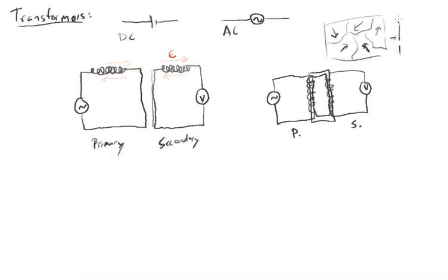When you magnetize it, what happens is all these domains line up. I can't draw the exact same ones, but if I put it in a magnetic field, they all line up. If they're like this, all their own little magnetic fields are canceling each other out, so there's no net magnetic field. Put it in a magnetic field that causes them to line up, and now not only do you have the strength of the magnetic field you put it in, but all the magnetic fields of the iron are lined up, and you have their magnetism adding on to the magnetic field you already had, and it amplifies it. So this iron core amplifies it, and it creates a stronger coupling between the two.